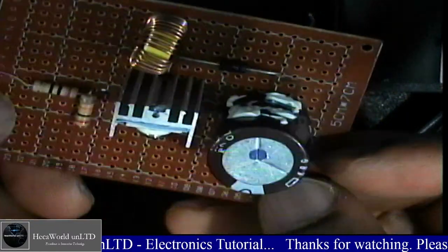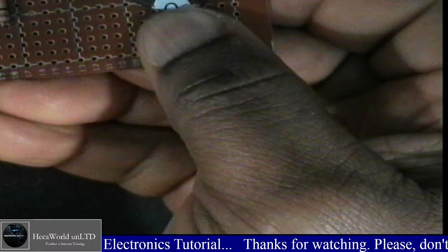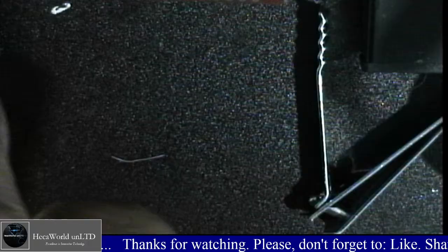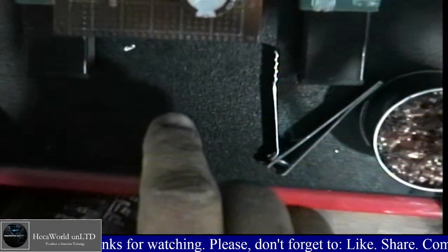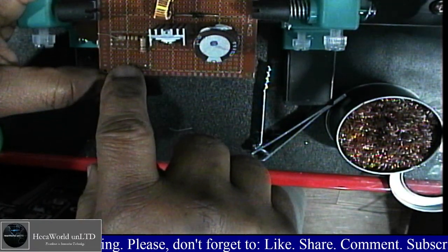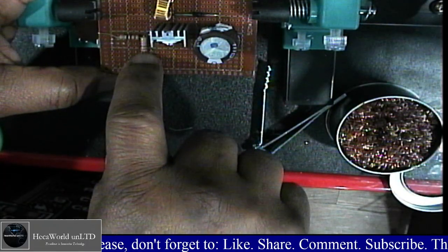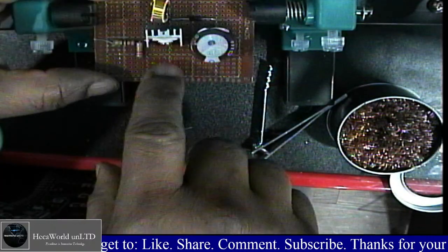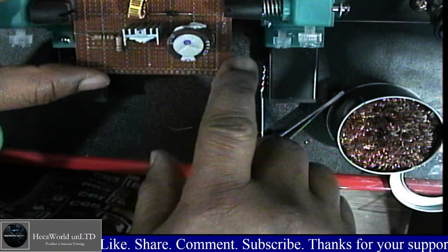So I'm gonna run a line for the ground. So both the input power supply, the 20K. Okay, I'm gonna zoom this back out so you can see where I'm showing. Yeah. So the input power supply is gonna come this way. I'm gonna run it through the 20K resistor, through the source. Yeah. Then through the capacitor, then to the output.